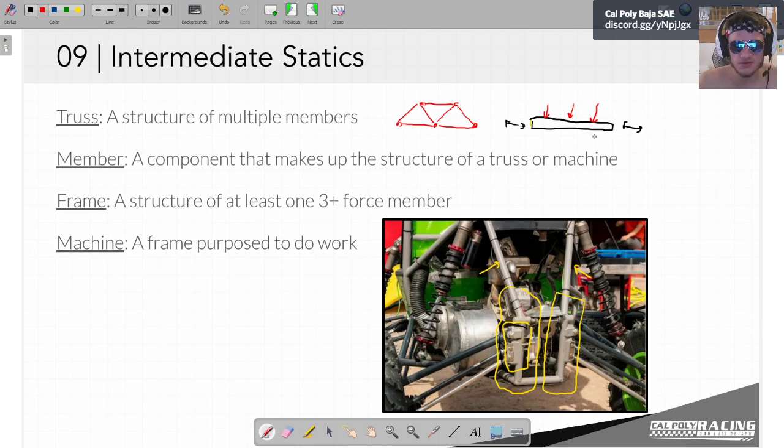One other thing that I didn't necessarily directly mention last time is that typically when we're talking about truss or frame structures, we're talking about things that are pinned at joints. The reason that we do that is we want to say that there's no moment that can happen, no possibility for these to be put in bending at the end of whatever your machine or structure is.